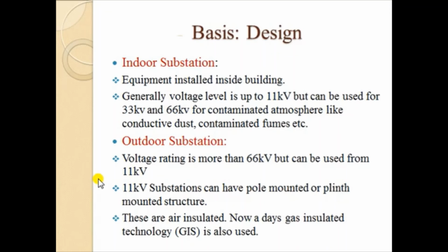Now, what is the basis of design? So, from a design point of view, a substation may be classified as an indoor substation or outdoor substation. An indoor substation may be required whenever you are not having suitable conditions outside, or there might be some different type of technologies also being used. For example, conventionally we use oil type transformers, oil filled transformers. If we are using dry type transformers, you can definitely install those transformers inside the building. So that is an indoor substation.